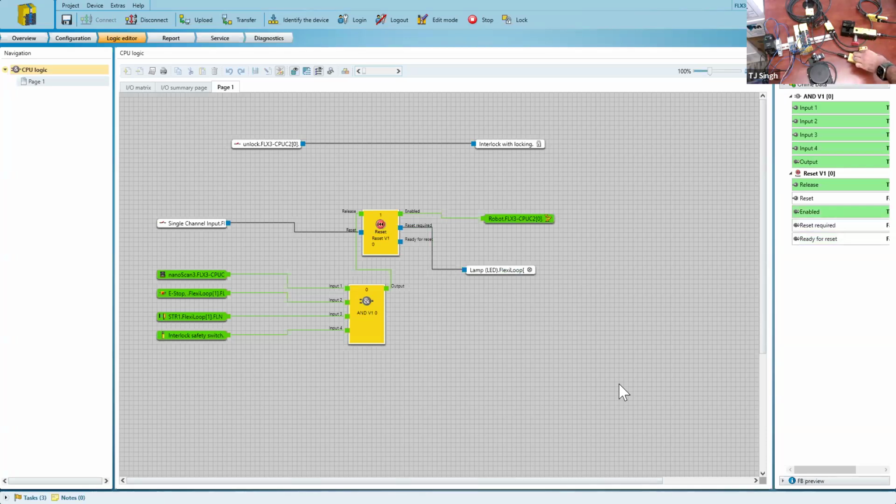But what happens if I take the non-contact safety switch away from it? Now it turns off the robot in this sense, right? Because it's turning off the safety relay. And if you can see it's red, now I bring it back and it should turn green on the software too, the flexi loop. And now what's it going to do? Hey, press on the reset and ready to go.